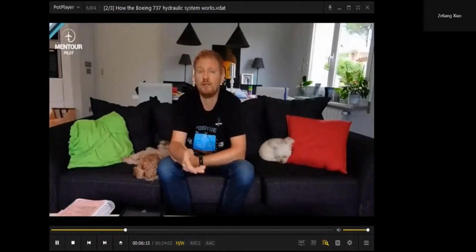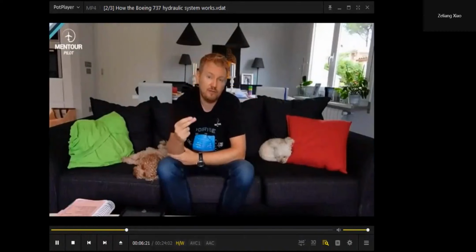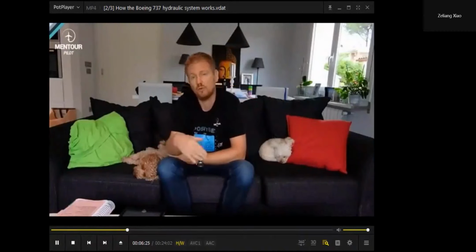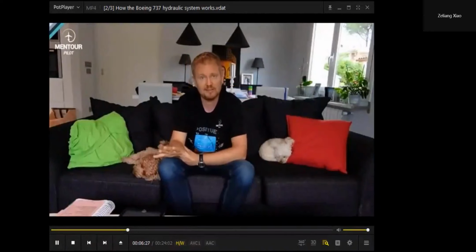So these are the switches, basically, and during normal circumstances, the engine-driven pump switches are always on, so they always operate when the engines are running, and the electric switches are off if the aircraft is being shut down for the night, for example. During turnarounds, we just leave the entire system on.